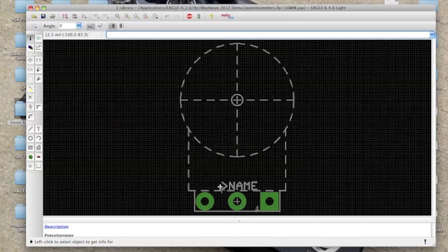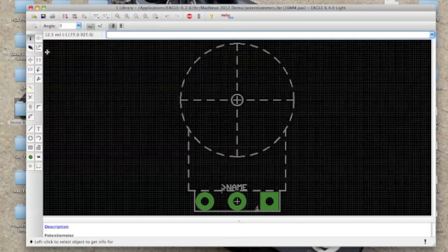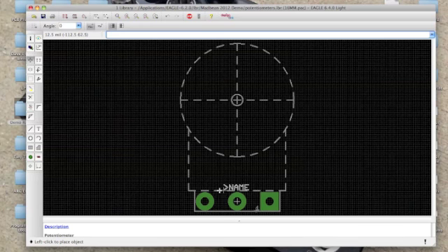If you're always resizing stuff on a part for names for your silkscreen layer, just do it once. Go into your part, edit the part, like that. I always have my names of pads sized at 35 mils. So what I do here is I just come in here, save it. Now every time I create a new part, this is how it's set up. See how that works?